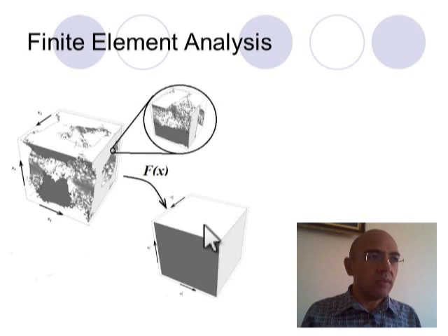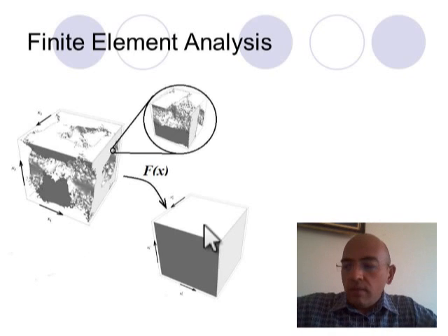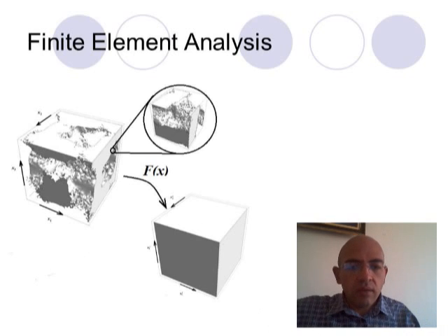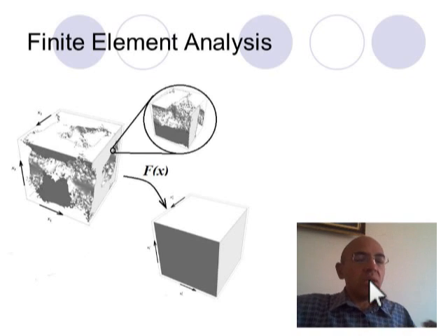We use material models, right? For example, if the material is elastic, we use the theory developed for linear elasticity. If we even want to predict the behavior of a composite material, then we use an anisotropic stiffness tensor and we homogenize the model, let's say. So we have a homogeneous model, and then we give it to the computer. So mathematics tells the computer that it's inhomogeneous, but the computer doesn't know it. So it solves just what we give to the computer.